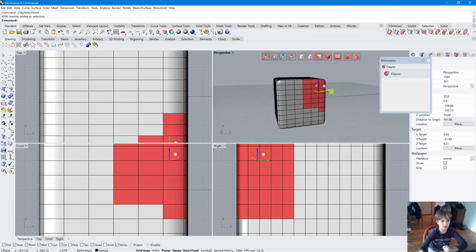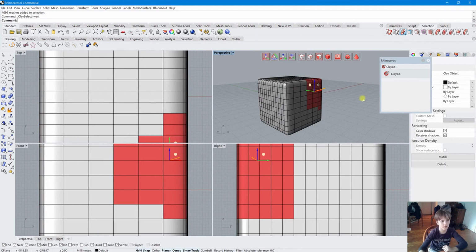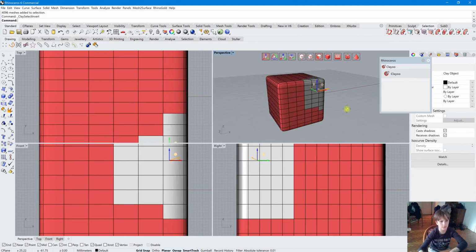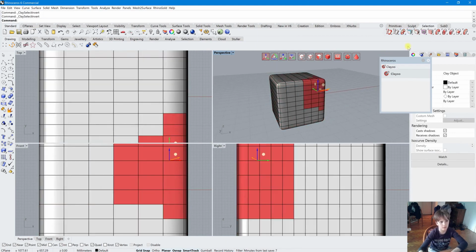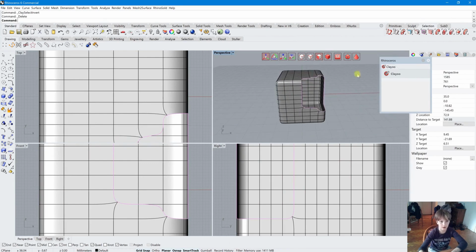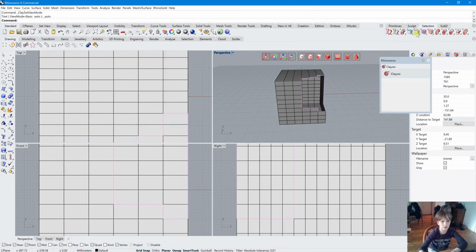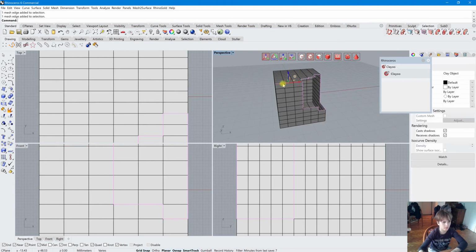Let's select a part and press invert selection. We'll select everything that wasn't selected. Invert. Next. You get a little hole. Try selecting edges, those sharp ones. Let's turn it on. It allows us to select edges like this.